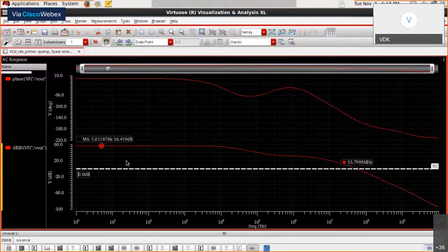So in that case, even with larger gain and larger length, the bandwidth also will be larger, no? No, the larger the gain, the smaller the bandwidth always. UGB, it is basically the gain bandwidth product. So L also needs to be iterated like this? It depends. If I need large bandwidth in my interest, then I try to keep L closer to the technology minimum. I make a choice.